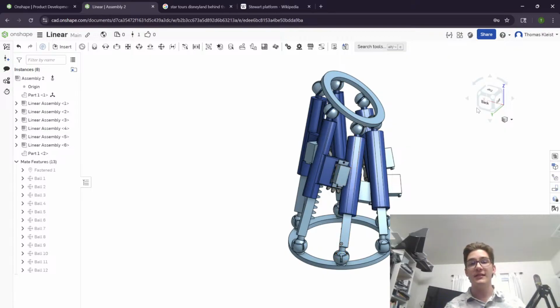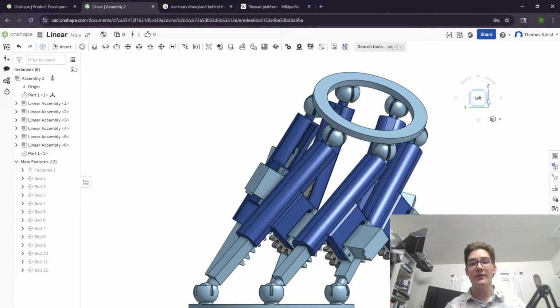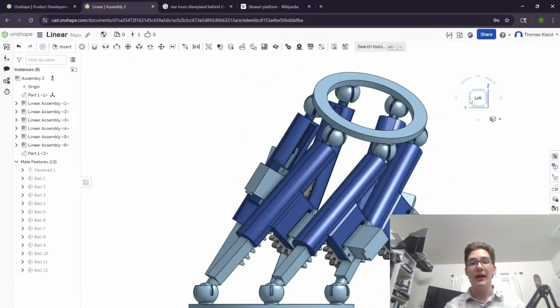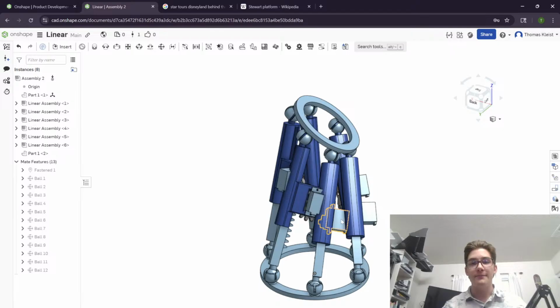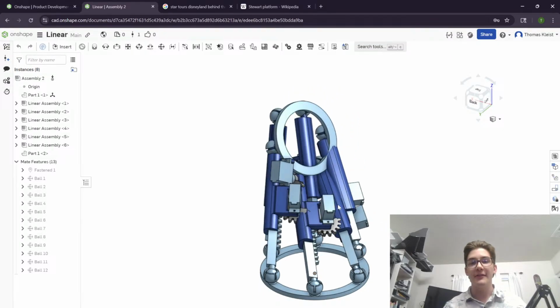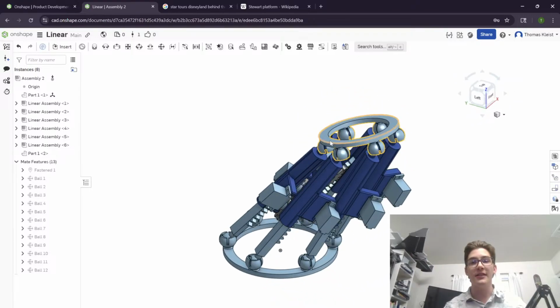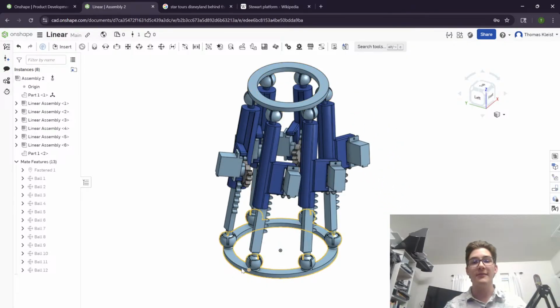One issue with this is you can see a lot of these actuators are sliding around, spinning around, and the servos are actually colliding. I kind of expect this to be a problem once I actually build it. So you can see how it's turning and colliding with the other ones. What might have been better is a ball socket for the top and a U-joint at the bottom, which would have constrained the rotation in the yaw axis. That way it wouldn't spin like this, and I could force the servos to face the outside.